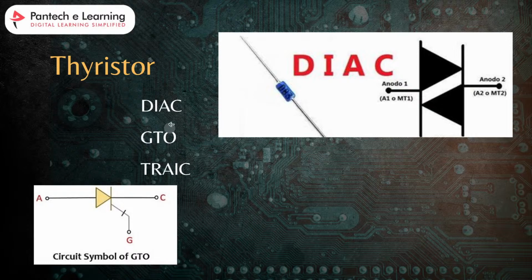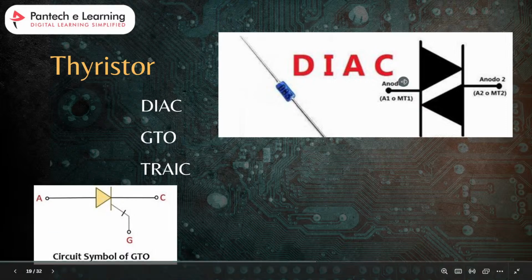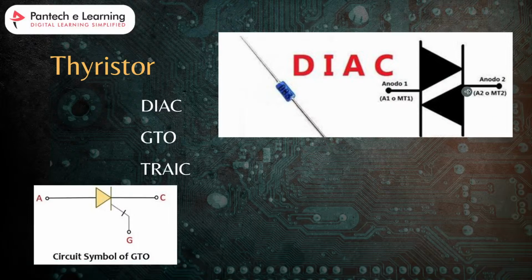So what types of thyristor do we have? Diac, GTO, and also triac. Diac is a special type of diode that works in both directions. So here you can see that it works in both directions. It is used to help trigger other thyristors or triacs in circuits. You will find a diac in things like light dimmers, where it helps control the brightness of the light by controlling the power flow. This is the diac.